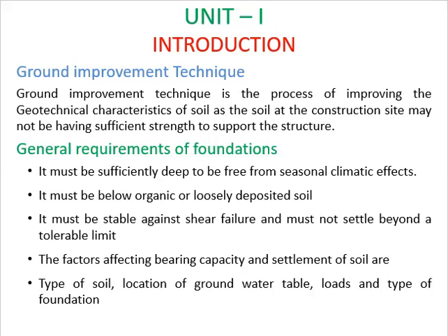Then what are the general requirements of a foundation? It must be sufficiently deep to be free from seasonal climatic effects. It must be placed below the organic or loosely deposited soil, if any. It must be stable with respect to shear failure and must not settle beyond a tolerable limit. The factors affecting bearing capacity and settlement of soil are type of soil, location of groundwater table, loads and type of foundation.